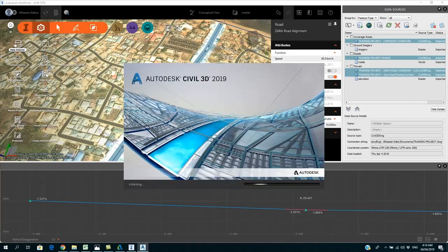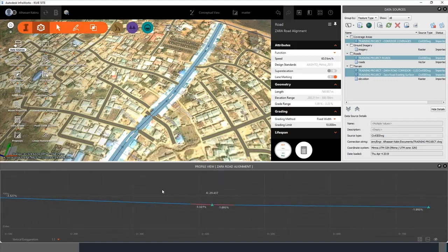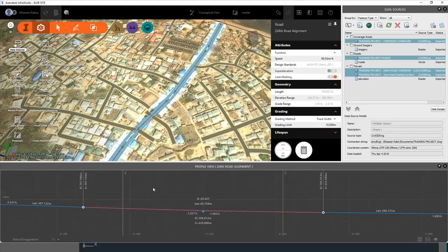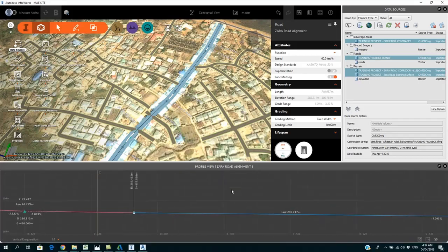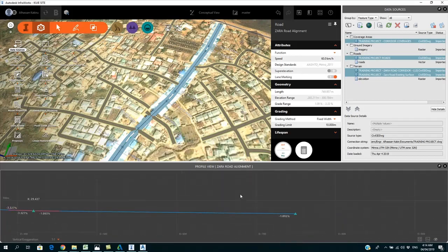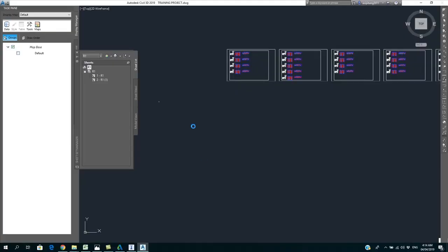So now what we have here, you can see I only create one sag curve. This is what we're showing here, and these are the details. You can see the K value. In this case, I can even do the same thing here, do modification here, and upgrade, create another curve pattern. You can see the length, and this is the endpoint. So it's based on the information you have in your Civil 3D that the information is coming up.